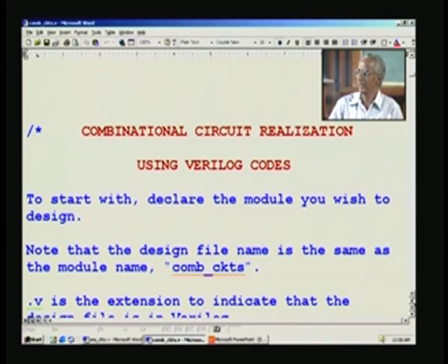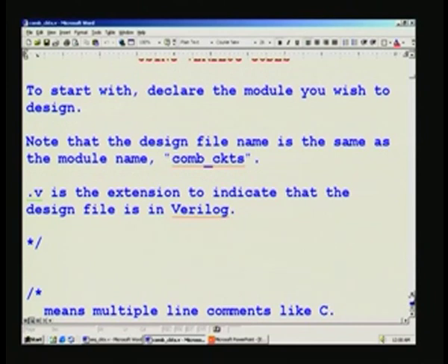We had to declare a module name, and what is new here now is that whatever you have as a module, your design, you will ultimately have to put it into a file, and when you make it into a file, give it the very same name that you have had earlier. For example, module_name was the name of the module that you have given for your design.